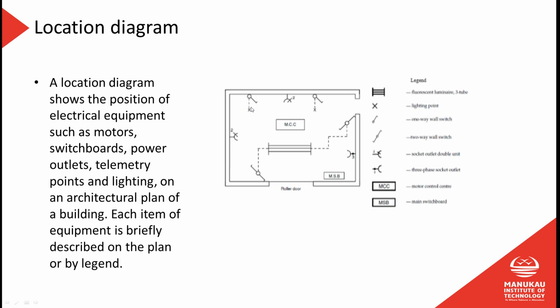here, for example, a single switch connected to some sort of light. As I said, there's a dotted line there that indicates that that switch is powering this light. Same over here. Those would probably be wall sconces or something. And then we've got two-way switches. We see they've got the two legs on them, which indicates that they're two-way switches. And the dotted line going up to a light, dotted line going up to the same light, so two switches powering the same light. It's our two-way switching, and that looks like a fluorescent fitting to me.